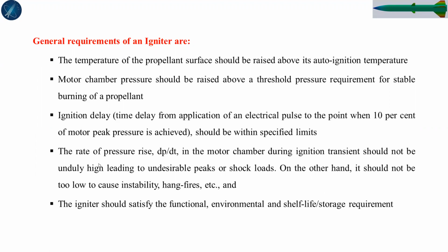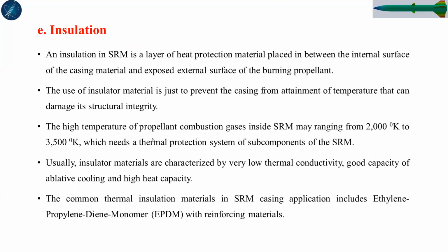The rate of pressure rise, dP/dt, in the motor chamber during the ignition transient should not be unduly high, leading to unstable peak shock. The igniter should satisfy functional, environmental, and shelf-life requirements.